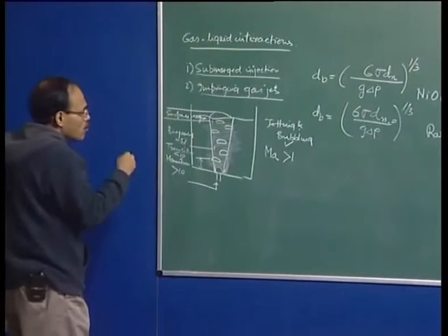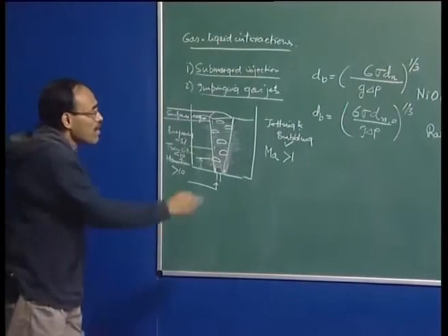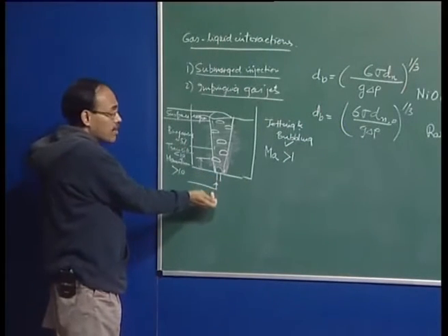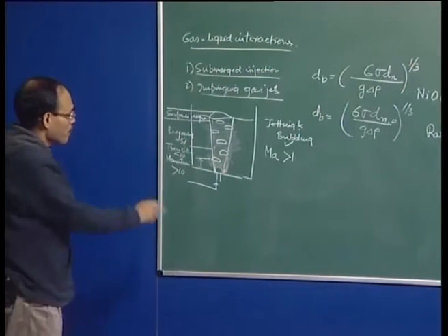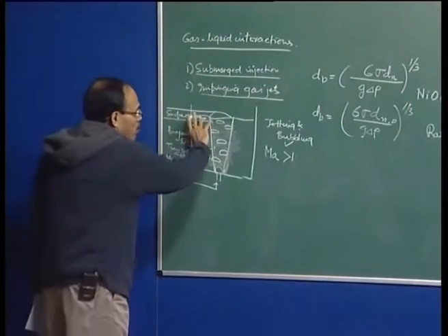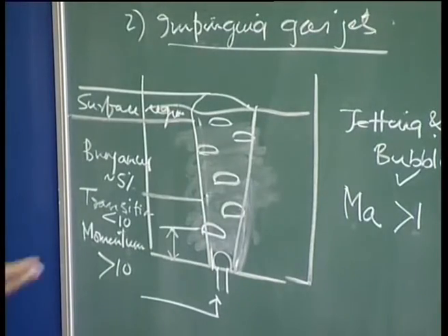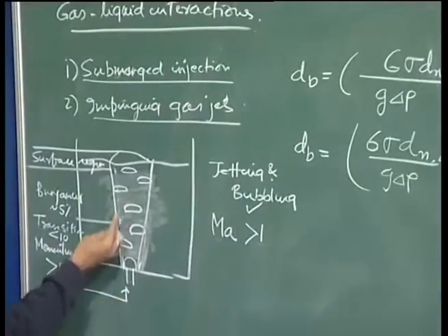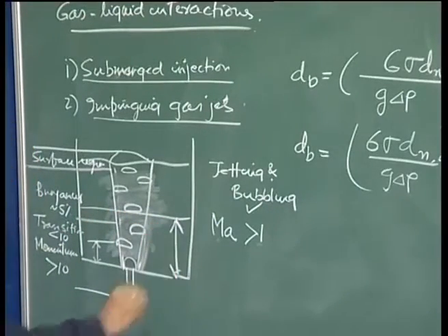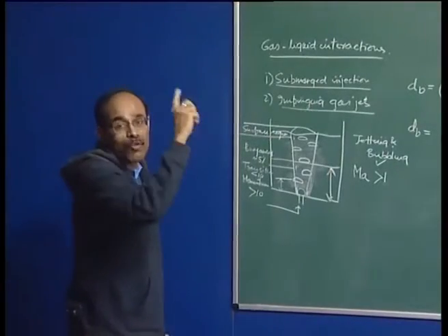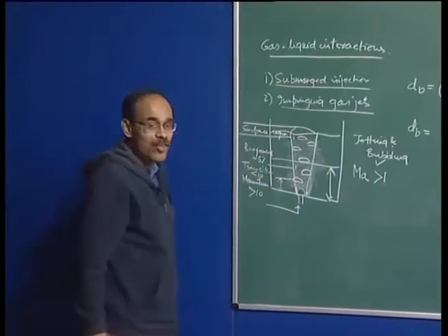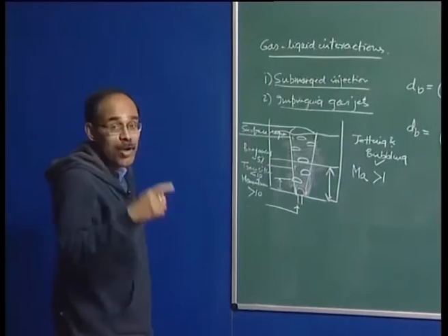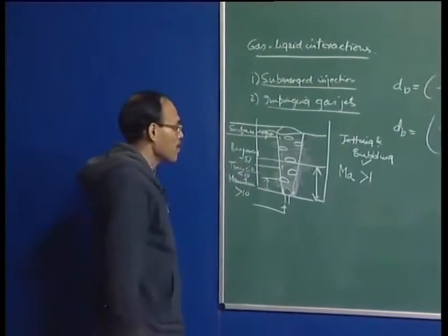A large part of this system is buoyancy. Therefore, the Mach number is much less than 1, and the free stream velocity is much less than 1. I will discuss this later, but the gas is injected, as I mentioned, either through a nozzle, a tuyere or a plug. When the buoyancy region occupies the major part, at low flow rate when the Mach number is much less than 1, these systems are basically buoyancy driven systems. One important characteristic comes when we are injecting a reacting flow in a small, shallow bath depth. Ladles and the like have bigger bath depth, but with shallow bath depth you have swirling motion. Even though this configuration looks two-dimensional or axisymmetric, with shallow bath depth and injection at high rate you can introduce a lot of swirling or rotational flows in the system, which can aid mixing in the process itself, and in OBM converters this is very commonly encountered.